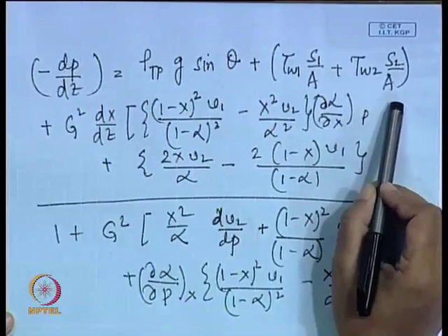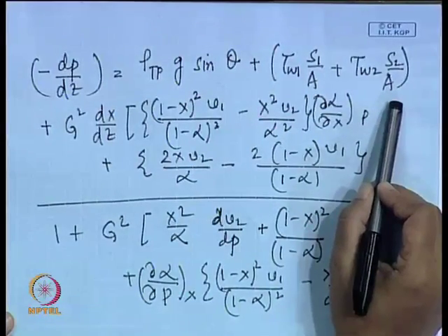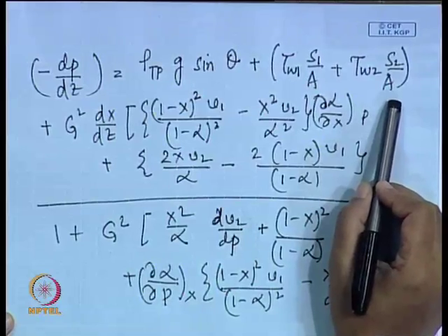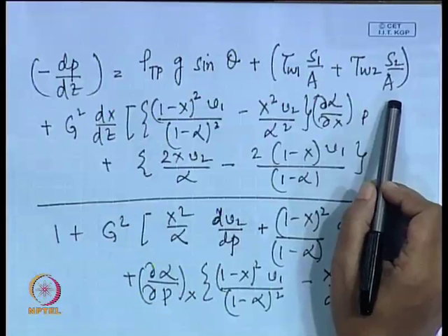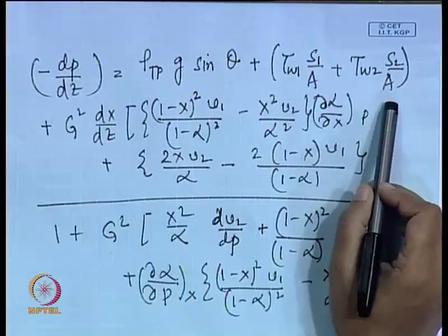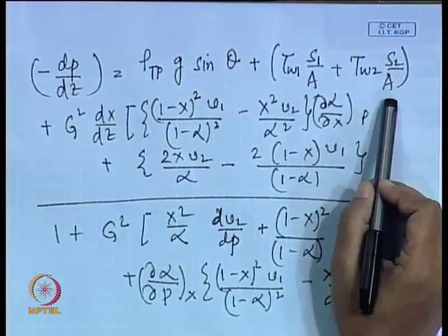Now, this had also created a problem in our homogeneous flow model. If you remember, there also we did not know how to express the frictional pressure gradient. Why does it become a problem? Because how the fluid will interact with the wall depends upon the nature of the fluid, upon the composition of the fluids, if it is a two fluid or a multi-phase mixture. Under homogeneous flow condition, the situation was simpler.